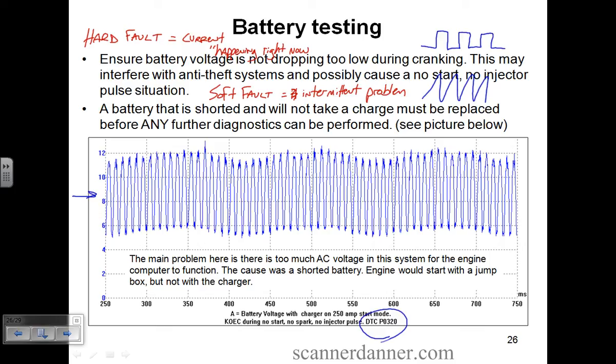And the battery is kind of an electrical cushion, if you want to call it that. And without that cushion of the battery absorbing these highs and lows, this is what was flowing through that whole system. DC computer systems cannot operate off of this. You got lows of under 6 volts and up to 12 volts. That's a pretty huge range.